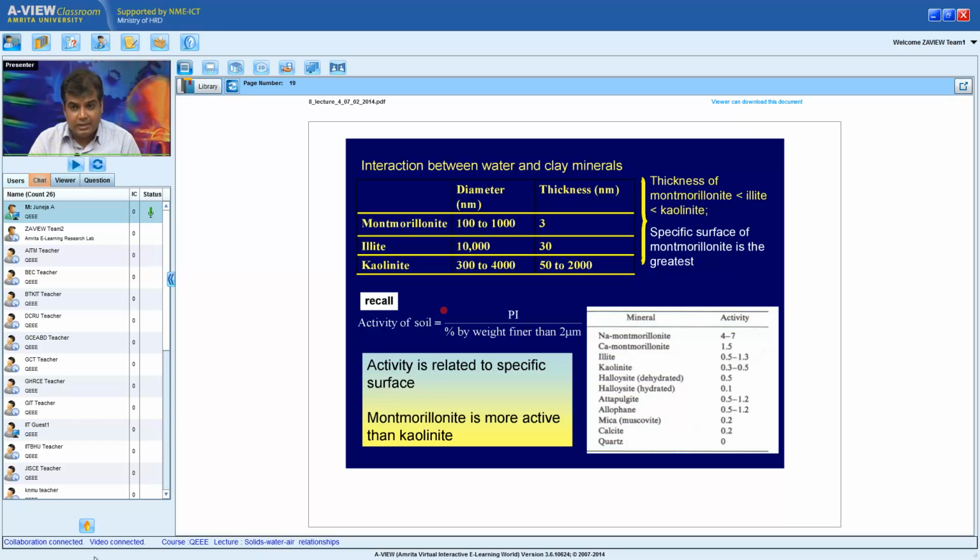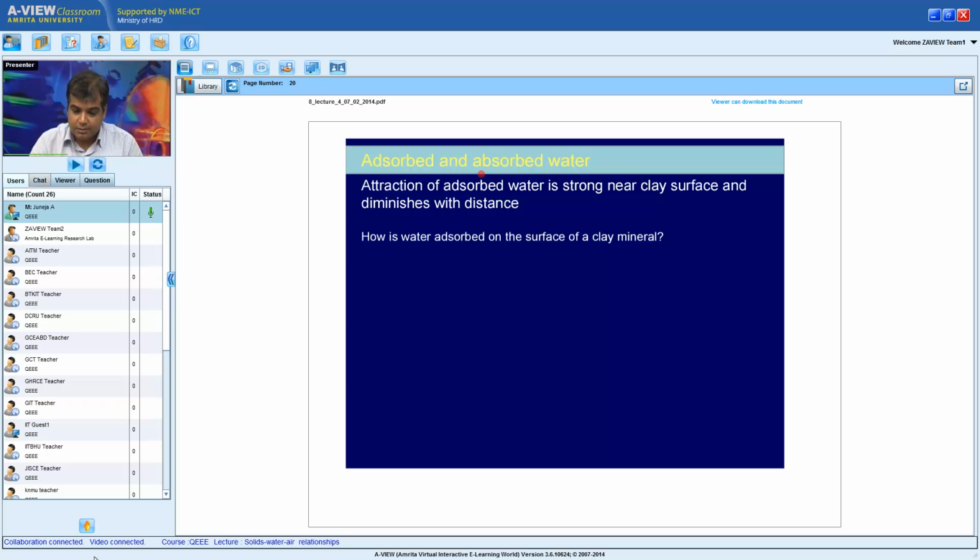That is easy. Having said that, if you don't have a dirty mix of clay minerals, the clay mineral is easy to identify in terms of these three. But many times nature gives us a lot of surprises, and you may have a mix of clay minerals or something which is not so common. But in majority of cases, engineers really get away by finding out the activity. Let's go to the next slide, please.